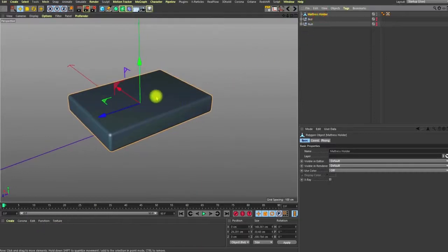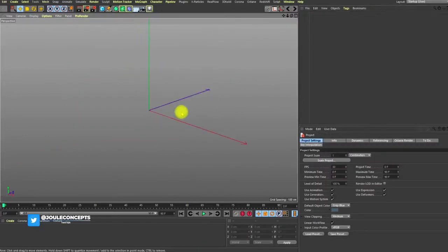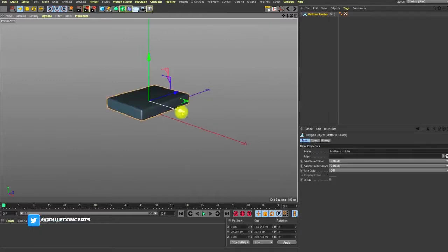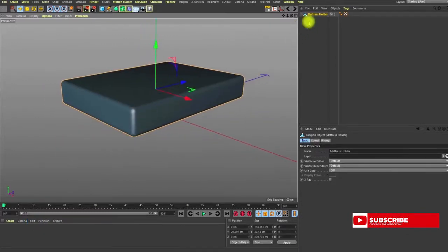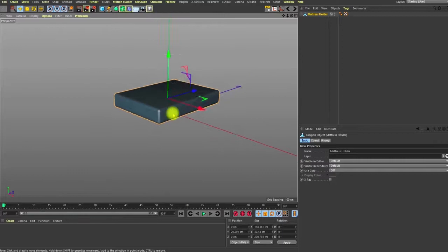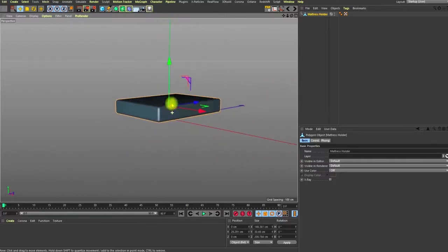Then I'm going to copy this, create a new file, and put this here. That's my own workflow. Even though I hid every other thing, notice it's not showing. The reason is because I'm using R19, so it doesn't give me room to export selected objects. Whatever object is in the scene is what is going to export out. So I have to bring it into a new file so that we can export it. We know that this is the only thing we have in this file.